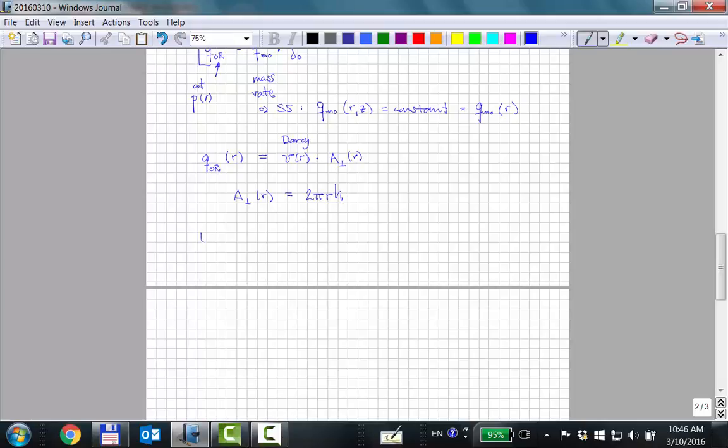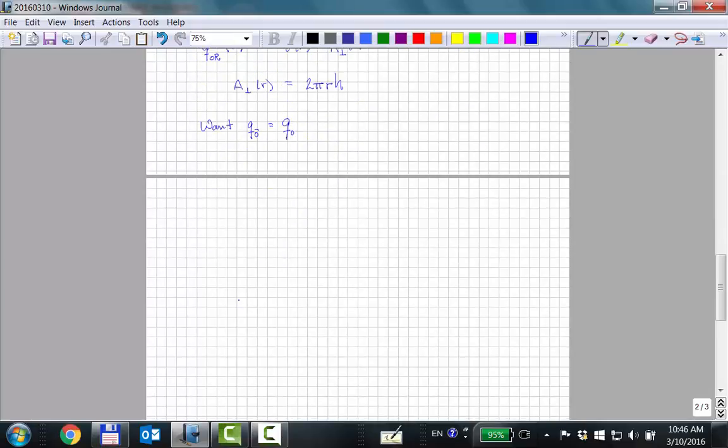And then what we want is the surface oil rate, which I'm just going to call QO. We want it in stock tank $40 barrel oil rates, not something that's 10% higher down in the reservoir that nobody's going to pay us $40 for. That's cheating. They meter it at standard conditions. They pay $40 for a metered stock tank oil rate, and that's what we want to use. So what's the relationship between QO and QOR, which we have? We have an equation for QOR.